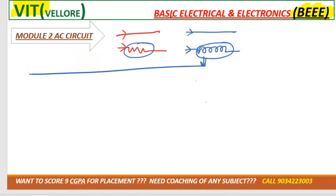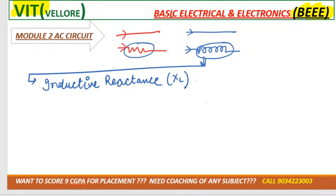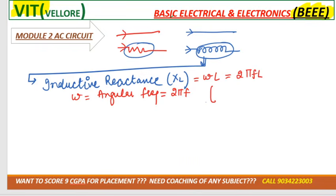So that resistance is technically known as inductive reactance. Inductive reactance is denoted by XL, right? And the XL formula is omega L. What is omega here? Omega is the angular frequency and its formula is, as you said, that is correct, 2 pi f. So XL is equal to how much? 2 pi f L.